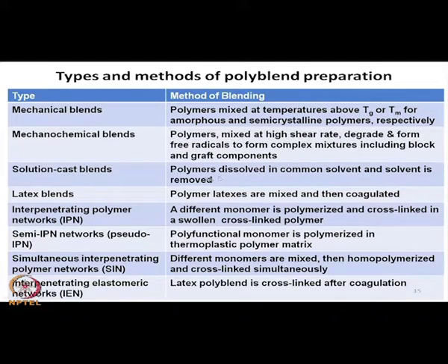So, in some cases we can use some solvents for solution blending. If it is not allowed, then we can go for mechanical blending or mechanochemical blending.